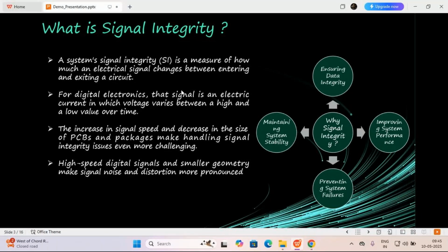So because of the changing magnetic flux from A getting linked to B, there will be some amount of voltage induced into B. Although there is no electrical connection between A and B, there will be some voltage induced in conductor B because of the magnetic flux coming from conductor A. Because of that induced voltage, we will get some noise on the 5 kilohertz signal in conductor B. Because of that noise, the conductor B signal will be noisy and it will lose its property, or lose its integrity.